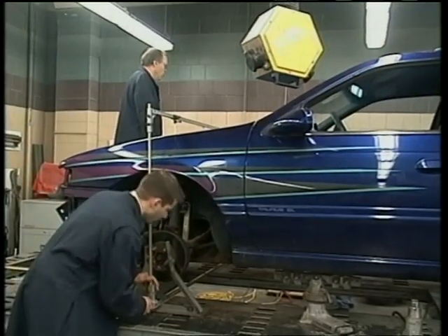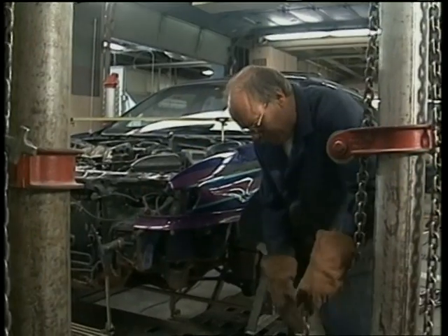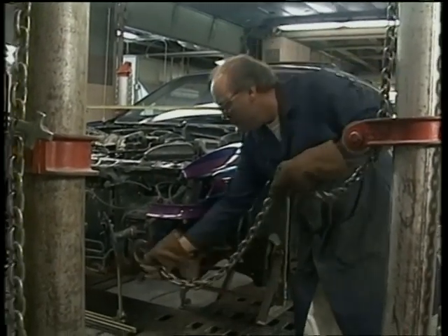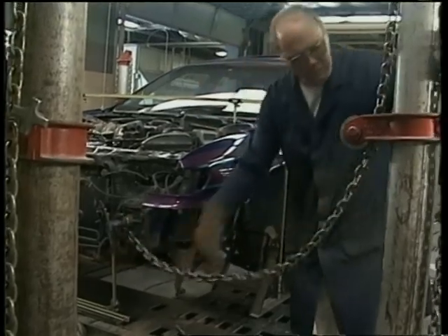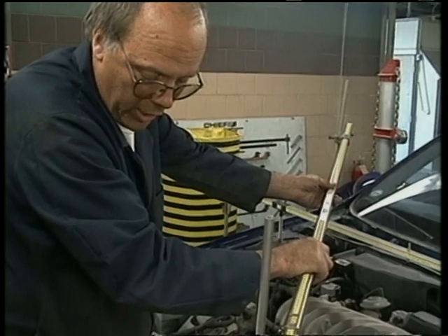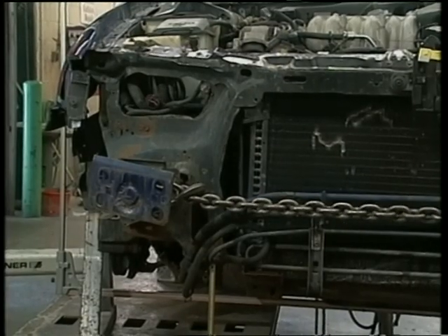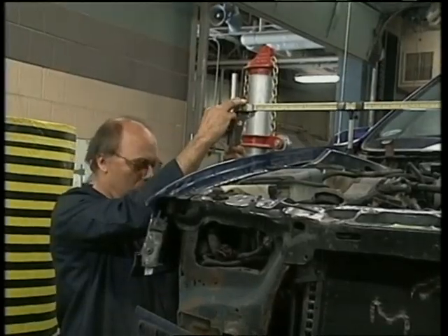Once you've carefully measured using the reference points and determined the need for body frame straightening, you can begin the straightening and alignment procedures. The body frame must be aligned first before you can adjust the wheels or suspension. Getting the frame into alignment is not just a matter of using brute force, but a demanding process that combines carefully applied pushes and pulls with frequent measurement. And as mentioned a moment ago, your measurements will need to be checked against the official dimensions for the specific make and model vehicle you're repairing.